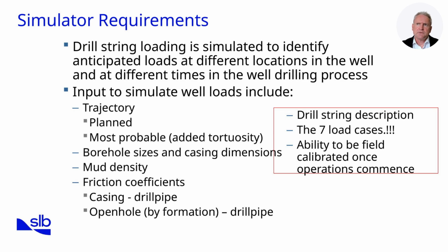Friction differs by formation type, mud system, and casing condition, so realistic values are essential. The simulator is then used to distribute loads along the drill string under these conditions, showing where torque peaks or where tensile stress approaches safe limits.